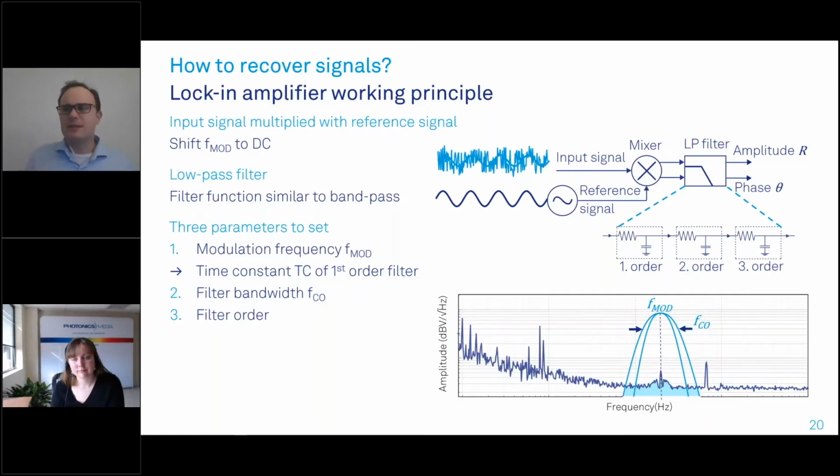I have to quickly think how I answer this in the best way. So first, what a square wave means. A square wave means if you make the Fourier transform of it, you will see a fundamental frequency, and then you have the harmonics of this frequency. This is what basically builds up the nice shoulders of the rectangular signal. It means that when you have a rectangular modulation, you do not only have the signal in one fundamental frequency, but also on multiple harmonics.